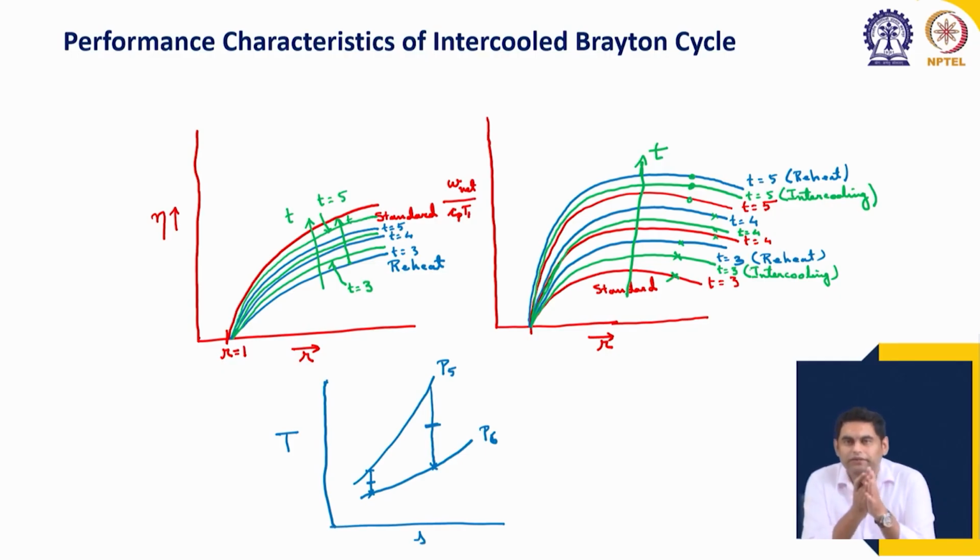Okay. So, to summarize, this intercooling is a process, conceptually it is similar to reheating, but practically it is a difficult process in the sense that you need a bulky heat exchanger, and you need external source of water, and this water needs to be supplied continuously for cooling. So, it removes the self independence of the gas turbine cycle, unlike say reheating, where we can inject fuel, because very small amount of fuel is needed, we can keep on injecting fuel for secondary combustion.